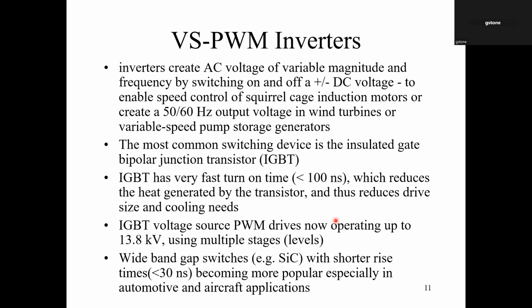I'm sure all of you listening to this are very well aware that when you switch a device, it's not when it's either fully on or fully off that you're really absorbing energy in the actual switching device. It's just when it's in the transition from off state to on, or vice versa. And of course, the semiconductor industry has been doing everything they can to shorten those rise times, because the shorter that rise time, it turns out, the less time that switching device will be heating up, and therefore the less effort we have to make to try and suck all that heat away,